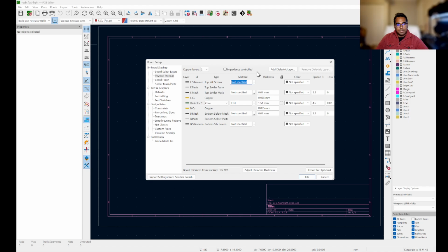If you are getting some kind of specialty board manufactured, you can specify the exact thicknesses of each layer in millimeters here. You can also specify the different materials that they might be made out of, but for our purposes, we can leave these at the defaults. FR4 is the resin substrate that just about all PCBs are made out of, some variation of that material. It's a very electrically resistant material that allows you to have components on one side that are not at all shorted to the components on the other side.